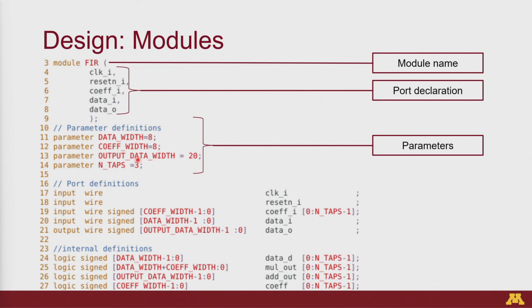So in this example, what is a parameter? A parameter says that right at the beginning, when we are synthesizing the code, we have fixed what the code is going to look like. So let's say a data width of 8. It says there are 8 bits in our register, and every single place where it's used will be 8, essentially permanently. If you make an 8-bit adder, it's always going to be an 8-bit adder.